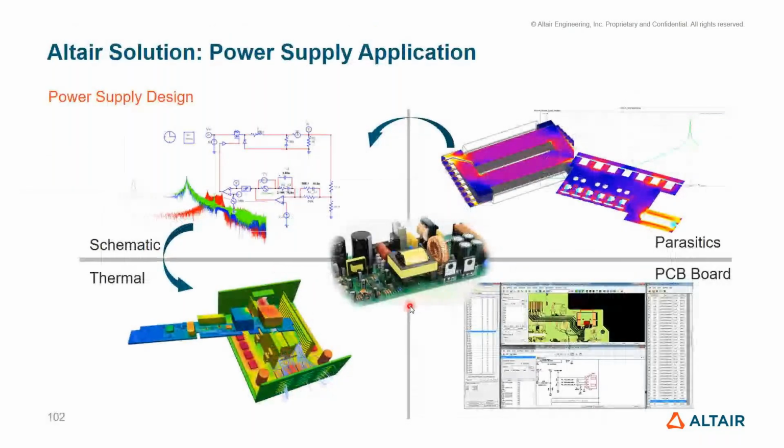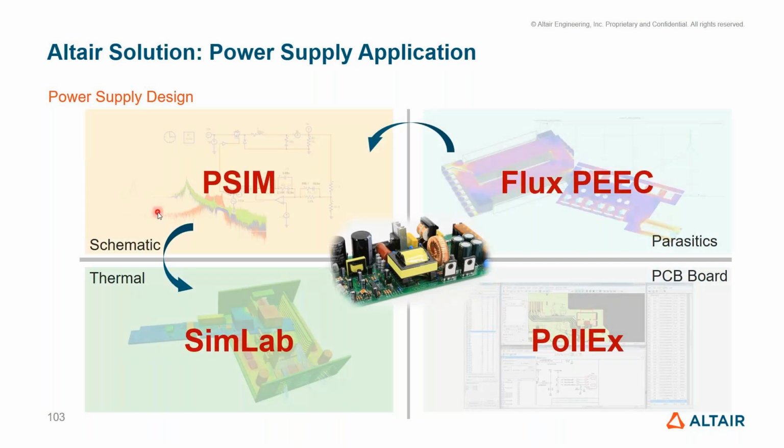Coming to power supply design, we have schematic, parasitic, thermal, and PCB boards. So the solution for all the four can be enabled with PSIM, Flux PEEC, SimLab, and PollEx. So PSIM for schematic, Flux PEEC for parasitic, SimLab for thermal, and PollEx for PCB board design.